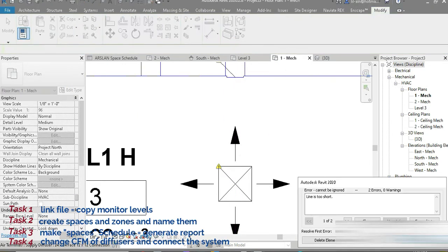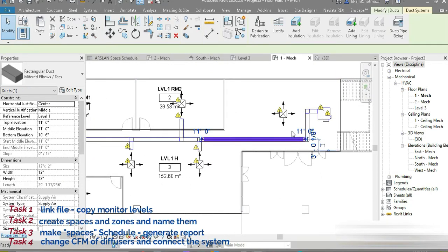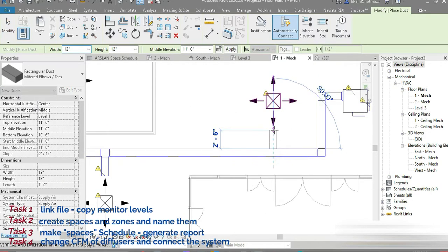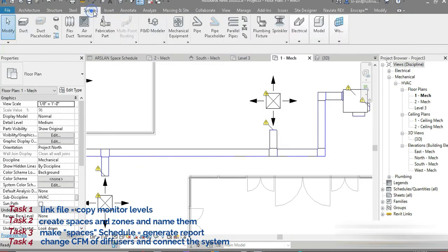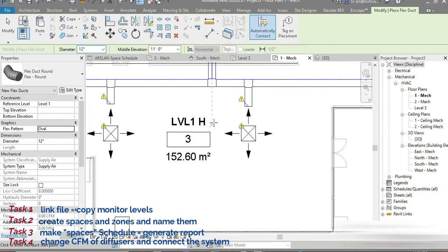So cancel anchor. Okay, that's enough, right? After that, once final one CS, which is create similar, let's click on that. Let's go to the system right here, let's go to the flex duct finally. You can change any shape that you want. Remember, this is 11 feet, that is at 10 feet. So you simply connect it from this to this and it's perfectly connected.